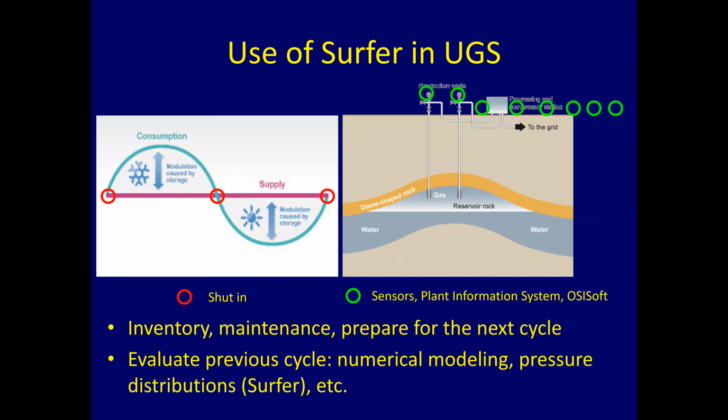And what we do during this period, we upgrade our numerical models, we make static pressure measurements, we make inventory, we make reports, we summarize the experiences which were gained in the previous cycles, and then we collect it, we make a little reporting, we discuss it with the storage side personnel. So there's a stronger communication between the reservoir group and the storage technical staff.